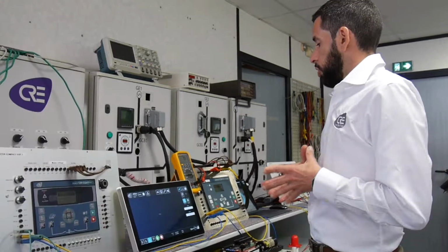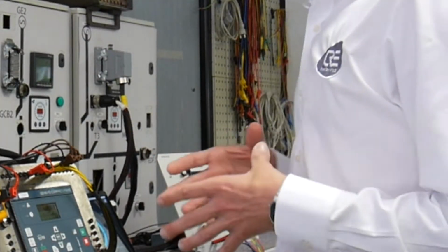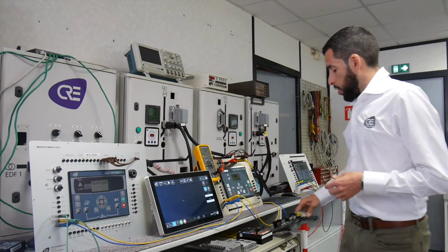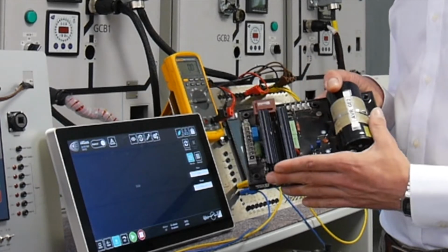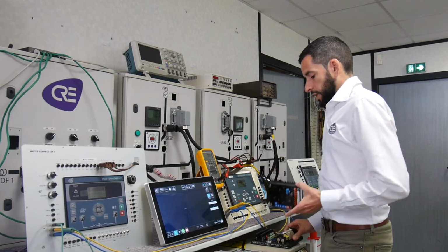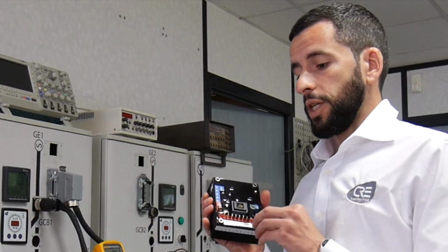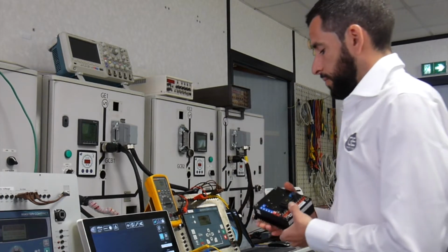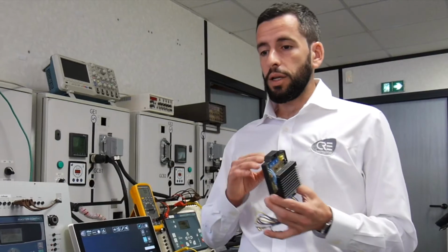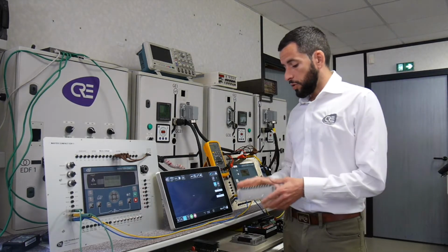What kind of AVR can we use? All of them. We can use all types of AVRs, whatever they are, electronic, digital, analog, or speed controllers, with EasyCalib. We can commonly see this kind of AVR in the market, which is a LoRa Summer one. This is a potentiometer input. This one is an electronic AVR that has pulse inputs, raise the voltage, decrease the voltage, to make the synchronization and the power factor control. And we have very simple AVRs like this one, which are made for very simple paralleling sequences like no-break changeover with the utility.